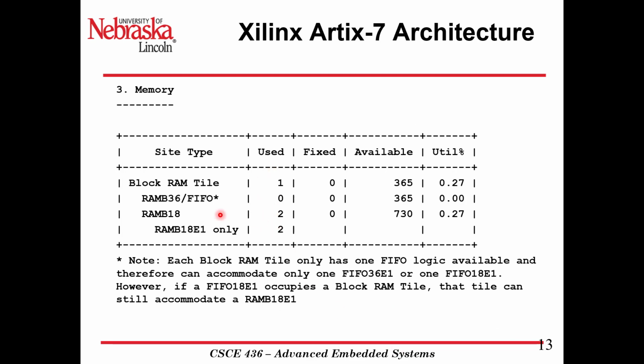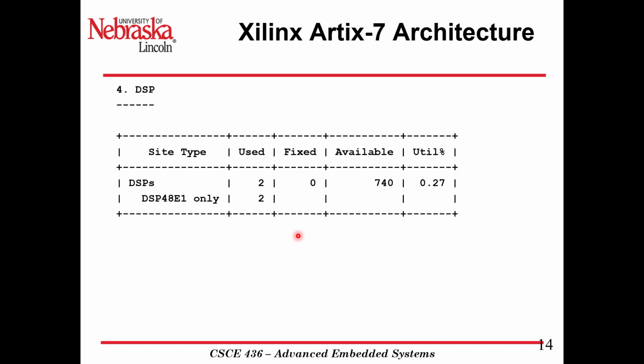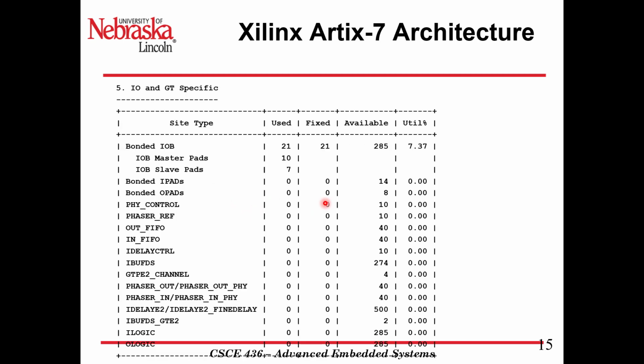Block RAM, RAMB18s. We're using 2 of those, which we're initializing with the 2 different lookup tables in there. And DSP modules. Some other stuff in there, you can take a look.